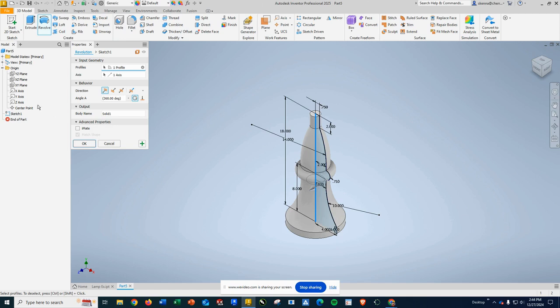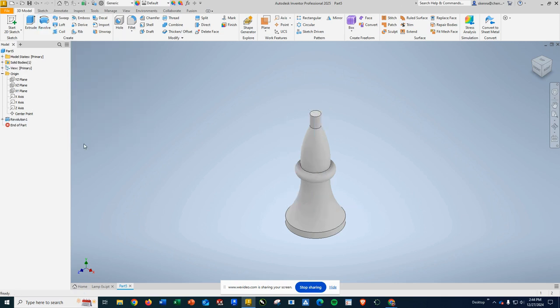Now, in this case, I am going to use one of the options we skipped before, where we create a solid that is its own solid. So we're going to call this base. This base is its own thing 100%. When I click OK, it will create it, and I will now have a solid bodies folder. When I drop that down, you're going to see base inside of it. That is important because as we add on to this, we're going to create them as separate objects so we can give them separate material looks.